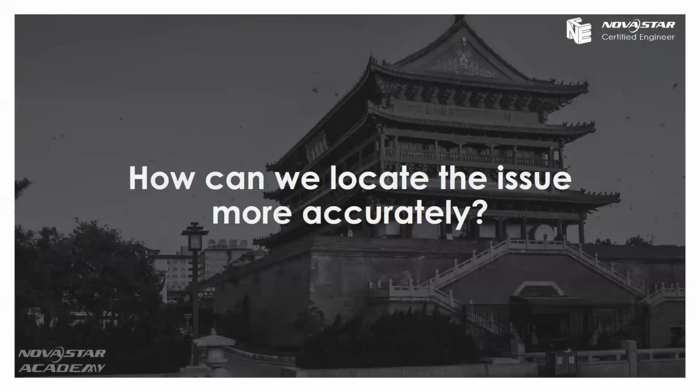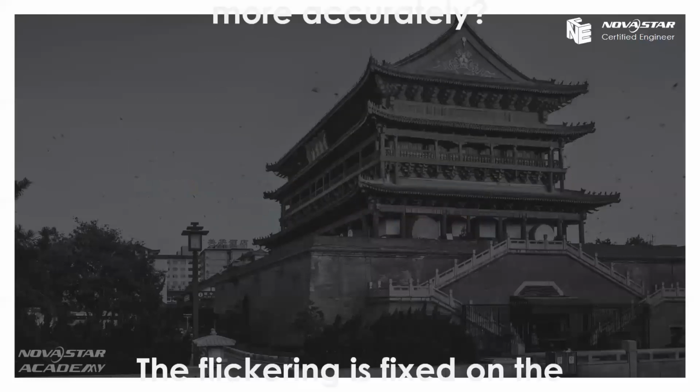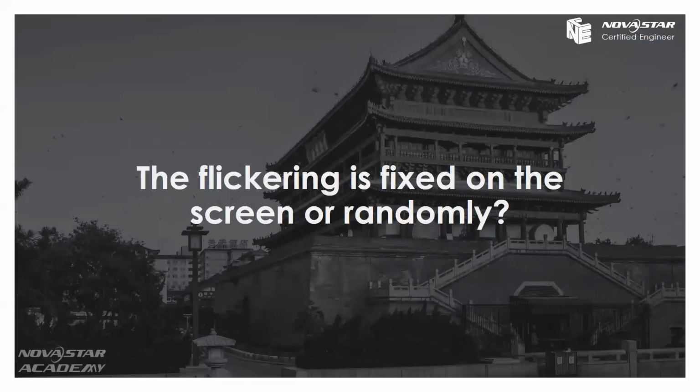Regarding the screen flickering issue, normally I will ask the customers one question. When the customer tells me, during phone support or remote support, that the screen is flickering, I will ask: is the flickering fixed on the screen or random? If it's fixed, we may have a way to do the troubleshooting. If it's random, or a full screen flickering, we may have another way. Okay, now let's see them one by one.